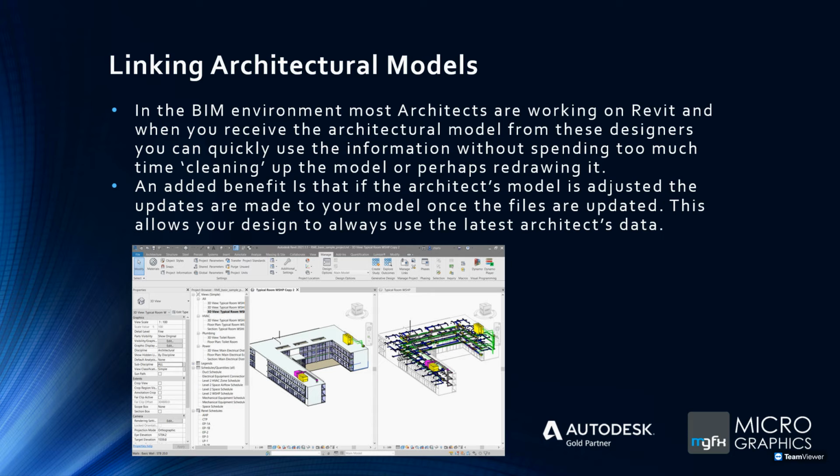But just by switching the environment from an architectural environment within Revit to a MEP environment, all the walls and the architectural components become grayed out and see-through, revealing your services. So you don't have to clean up much. The components and the walls and the ceilings, everything is there. They're just half-toned or see-through, and that's just one setting that you change.